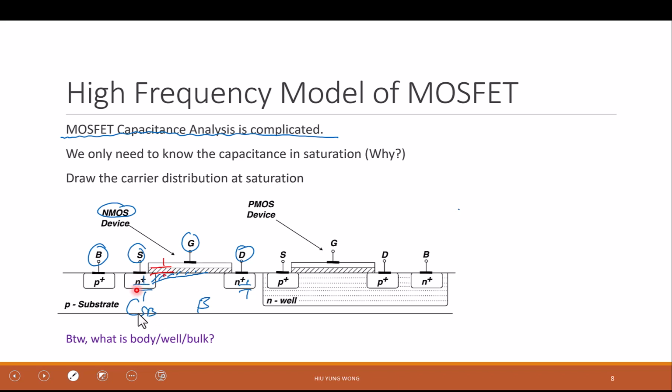And here you tell me that it is the depletion layer forming the insulating layer, right? For the junction. What is the insulating layer for this capacitor? The oxide, just the gate oxide. It's an insulator, right? I have a conductive metal on the gate and then a conductive inversion layer full of electrons. So there is a capacitor.